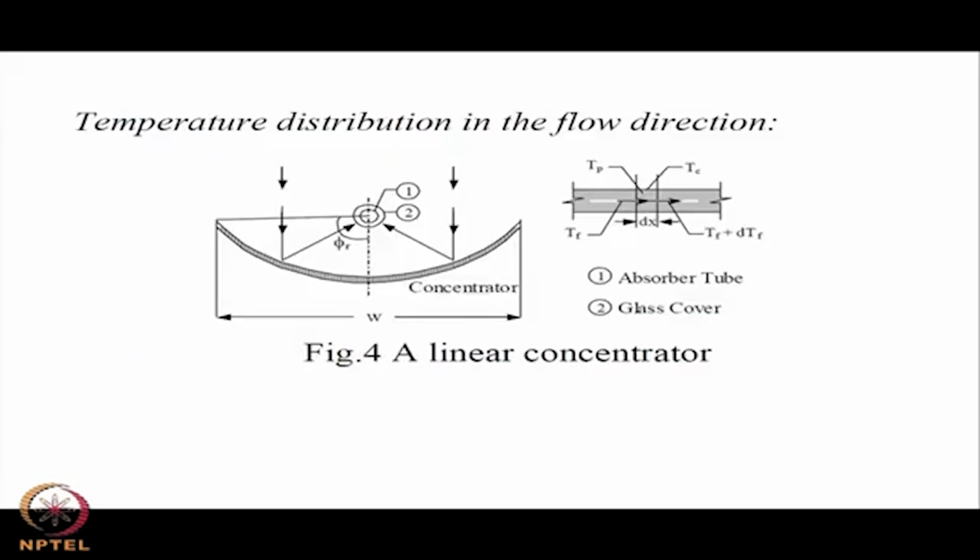So, this is what was a bit confusing, in the sense that last lecture I was mentioning circular or linear interchangeably. The whole point is the circular concentrator has a higher maximum possible concentration ratio, the maximum being 45,000, and the linear concentrator has a maximum possible 212.